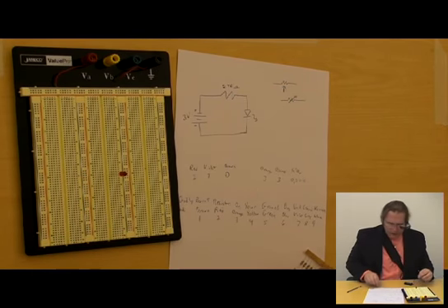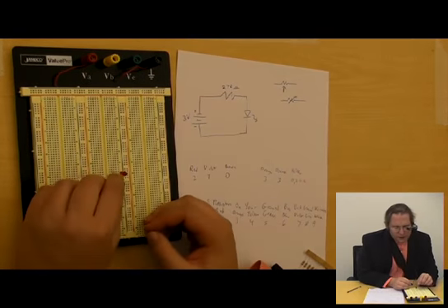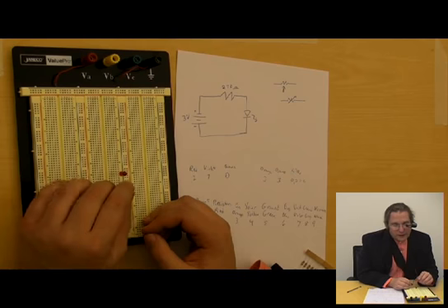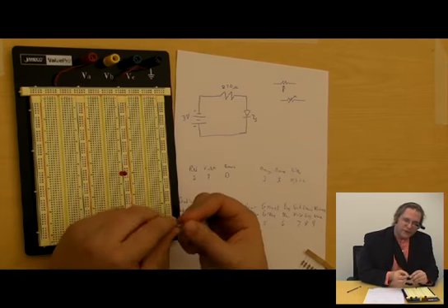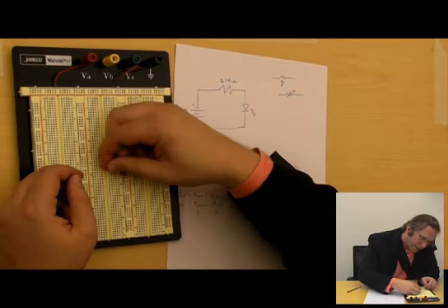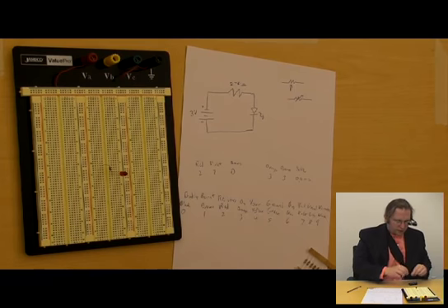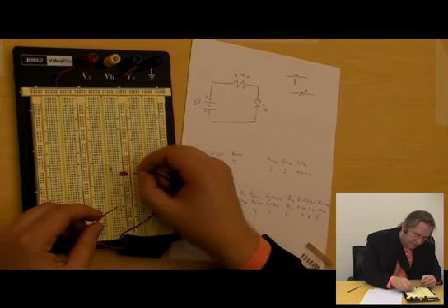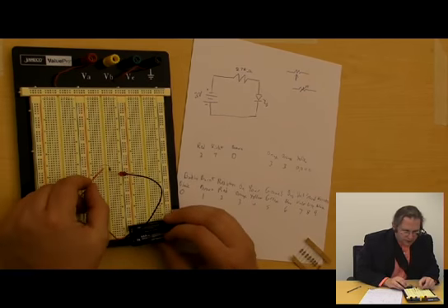And I'm going to put my resistor in. Now, you do not want to put an LED directly onto a battery because it'll burn out. An LED that allows too much current to go through it will burn out very quickly. So I'm putting this resistor in there to keep it from burning out too quickly. So put that there, and now I'm going to test the thing out. Let's see if I got it the right way.